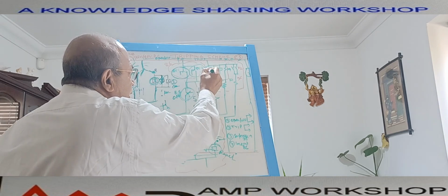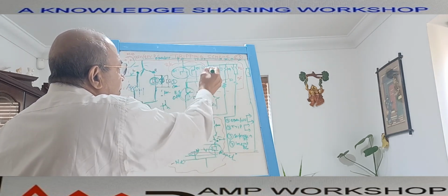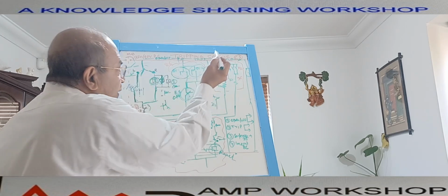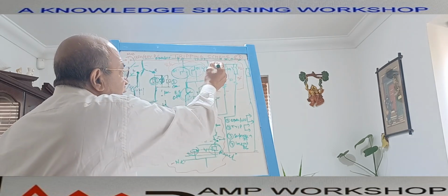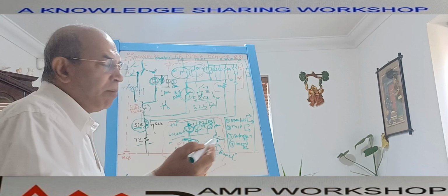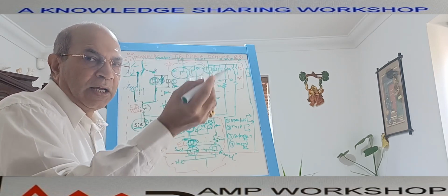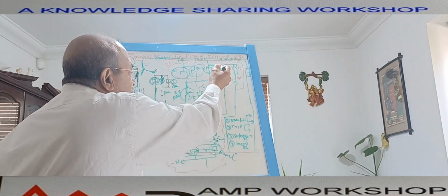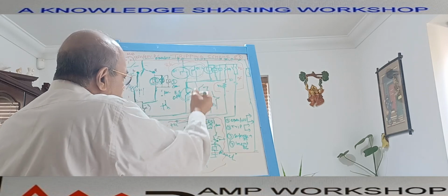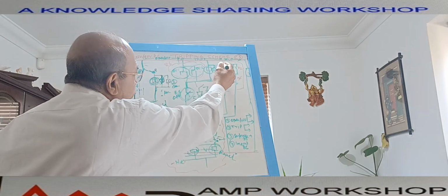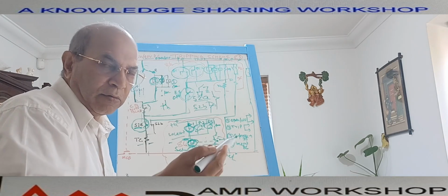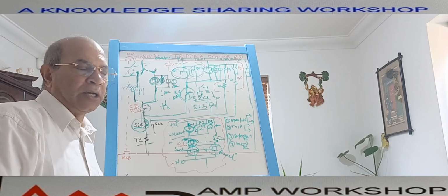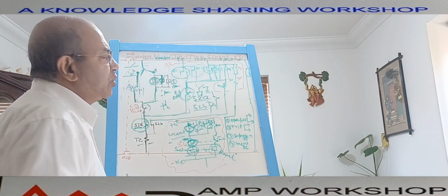Then that emergency shutdown signal can also do the same operation. It can trip this breaker. Suppose an intertrip is required. From that remote substation, they will issue one intertrip command, because there is also a lockout relay. That remote end lockout relay can give a tripping command that we can connect over here, and it will go to the tripping. So this way also, from the other device or other location or emergency condition, this circuit breaker can be tripped.